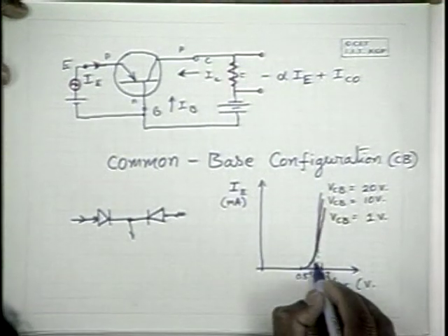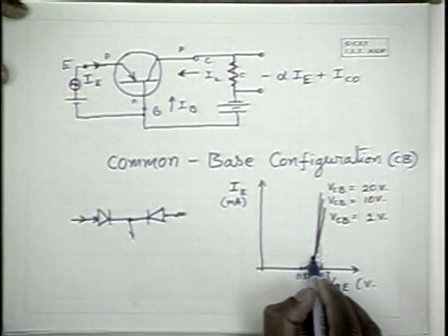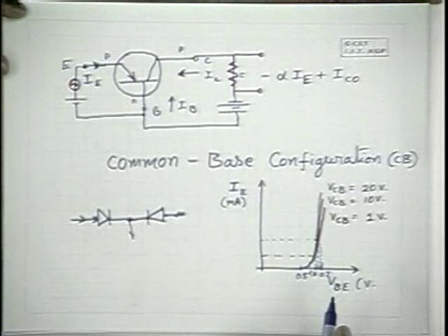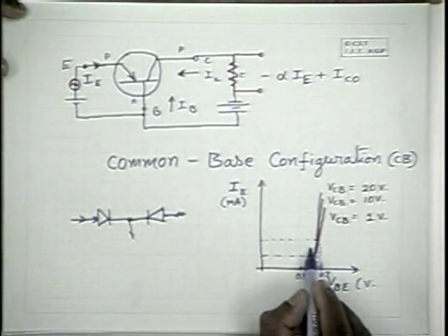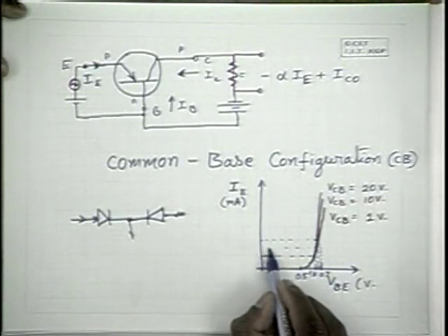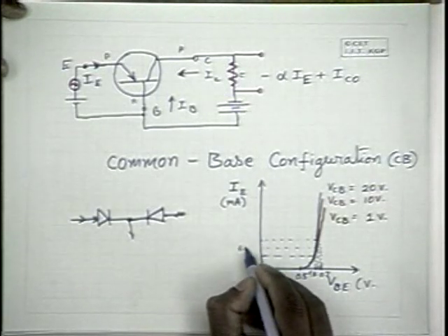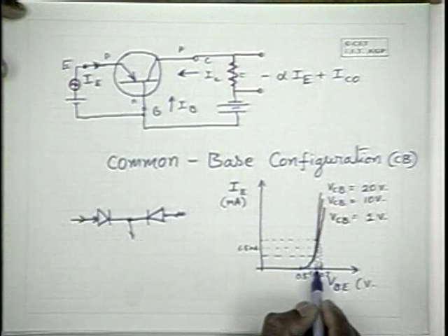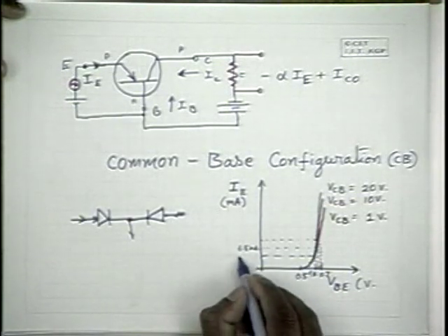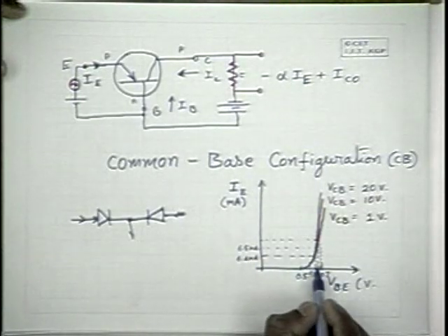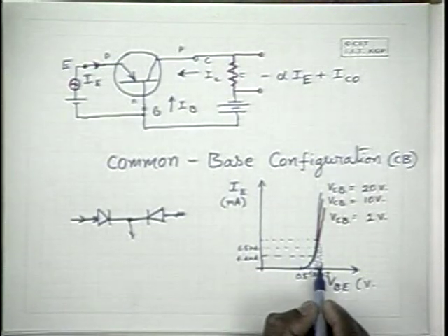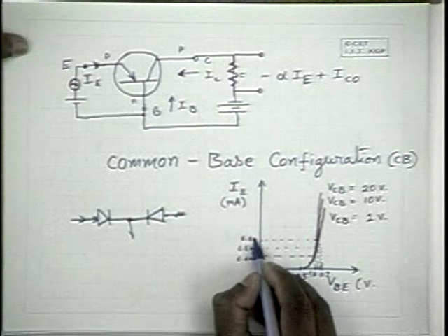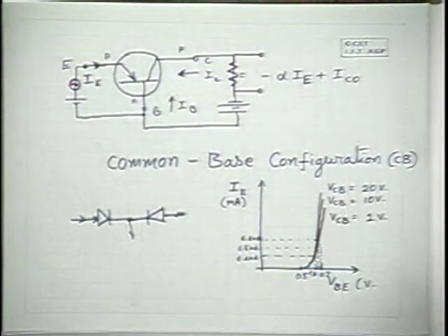So with this voltage variation in the base to emitter, you get a corresponding current variation in the emitter current. Say at 0.65, it provides you 6.5 milliamperes of current, and with 10 millivolts negative it would be 0.64. With 0.64 volts, say you will get 6.4 milliamperes, and 0.65 plus 10 millivolts, when the AC signal is positive, it will go to about 0.66 volts, and the collector emitter current is say 6.6 milliamperes. This is a typical example I am taking.